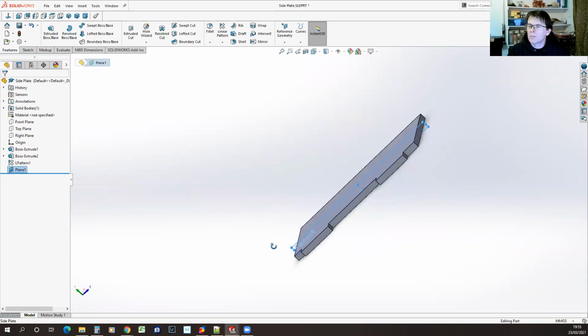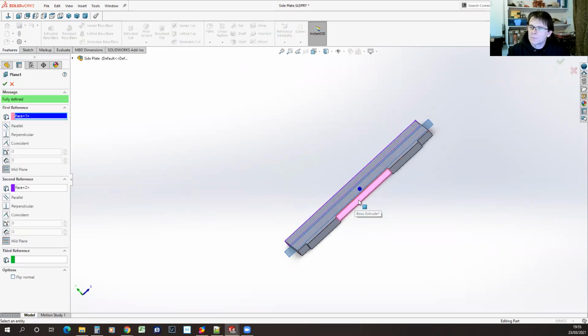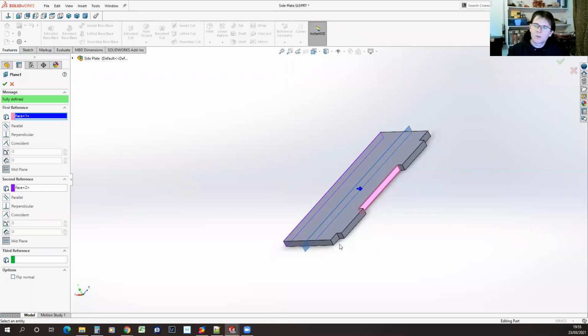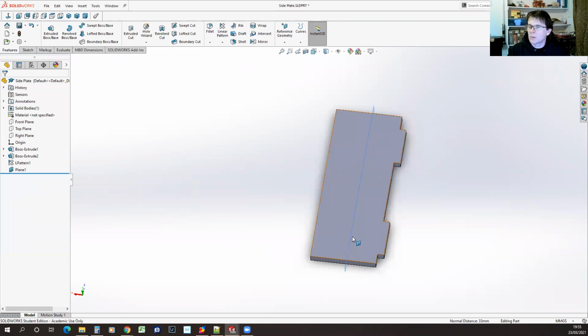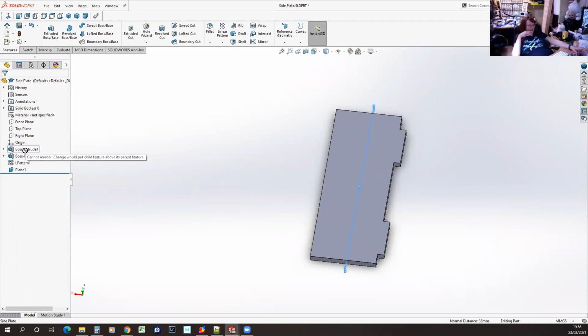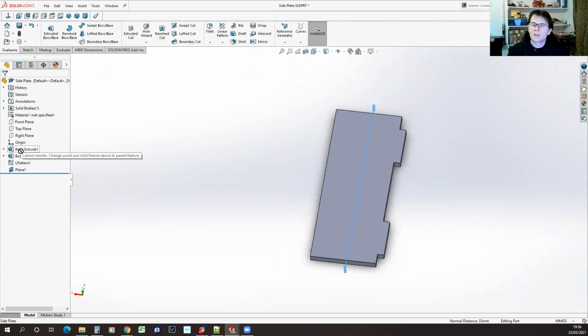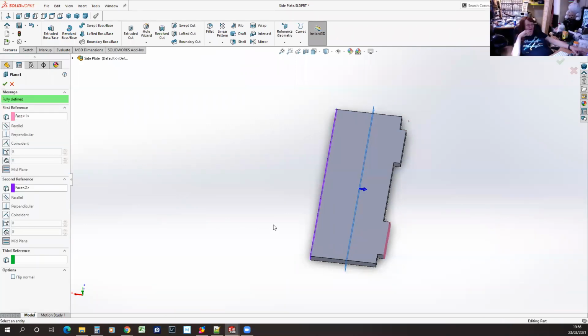The reason I was wondering whether it may not is that this face here is actually not one continuous face anymore because I've got that other feature. And sometimes when you click on a feature, my midplane no longer appears in the middle because it's now halfway between the tip of that tab and that edge. There's one more thing. I now can't move it up to the top because it depends on this second feature. I think the time has come to introduce rollback.